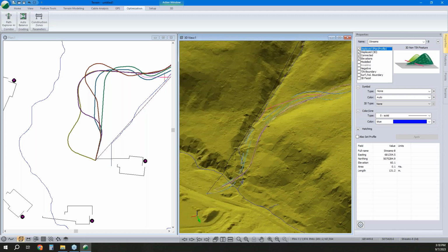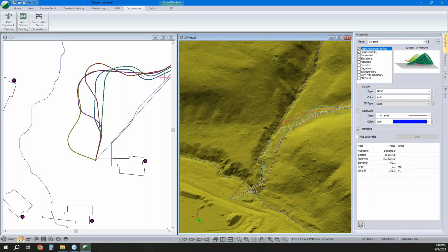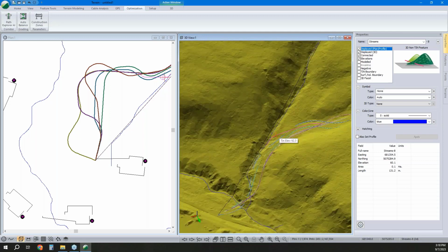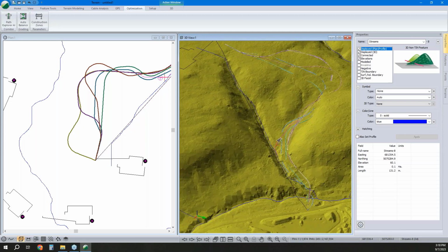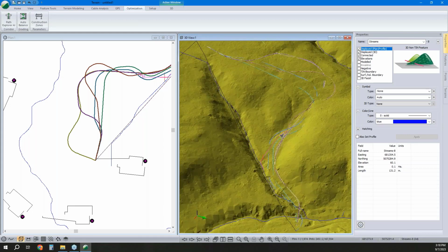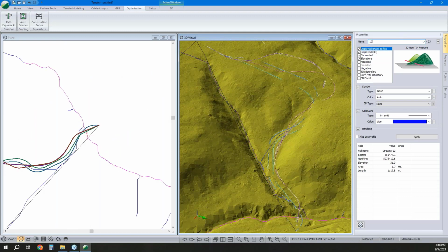I'm going to add a no-go because I don't want to have that cross right at where the streams junction anyway. So I'm going to make a no-go area here, and the other streams I'm going to just weigh the expected cost to cross them. So add an additive cost into my unit costs. So this stream here, I'm going to change my name so I can keep track of it. I'm going to say that's going to be $2,000 to cross that one. I'm going to say this guy here is probably $4,000. And this guy here is probably, well, it's a biggie, so we'll go 10.